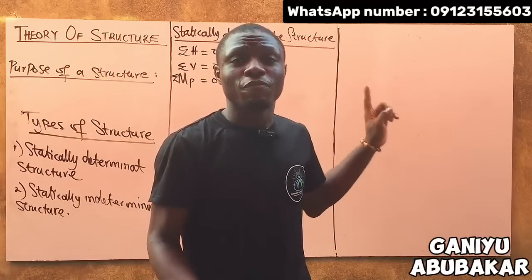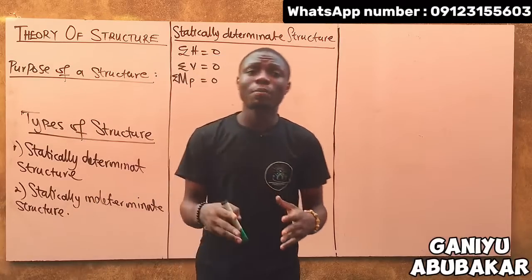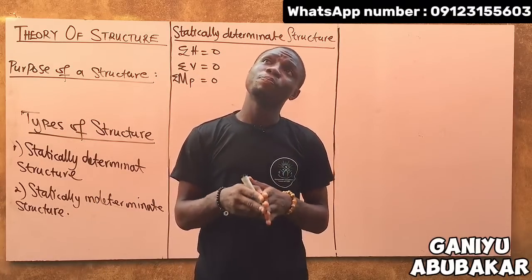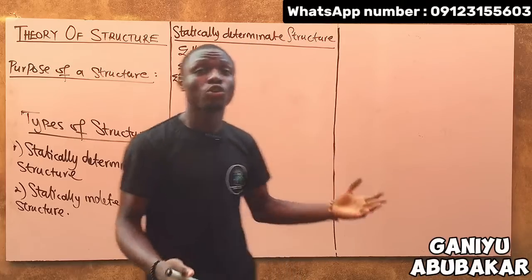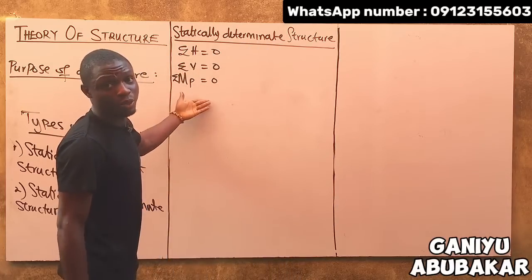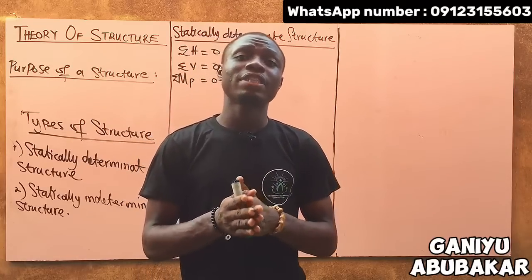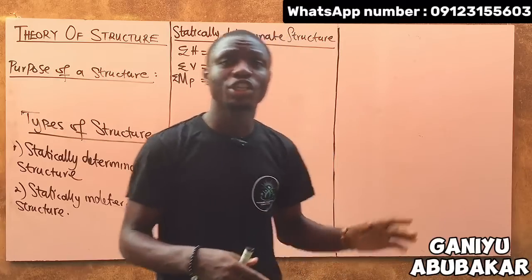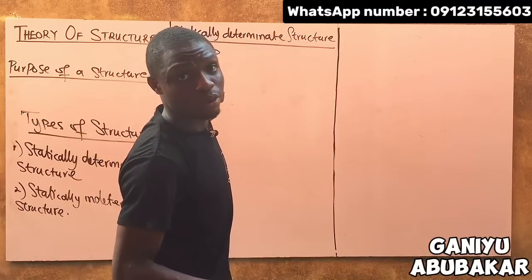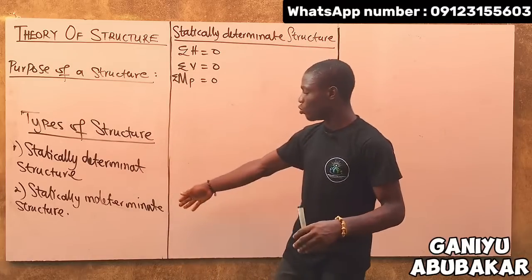So the statically determinate structure can satisfy the conditions of equilibrium. Let me put it that way, right? Statically determinate beams are those beams whose reactions can be determined using the equations of static equilibrium.